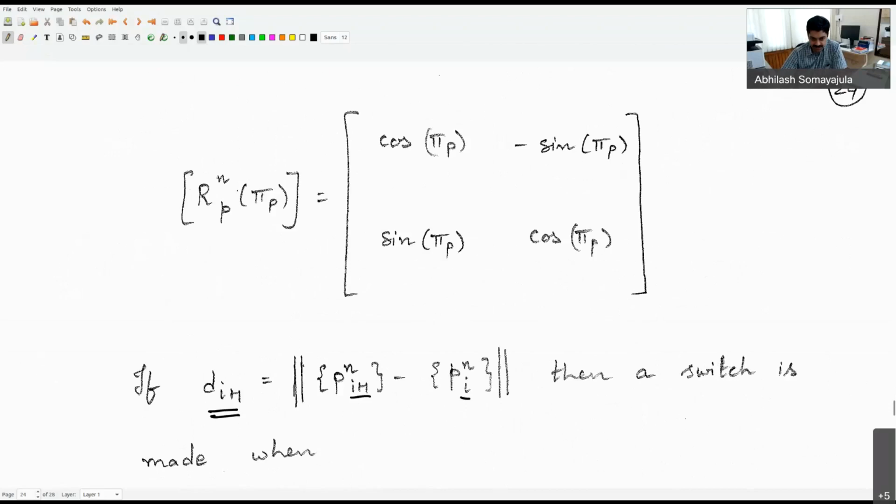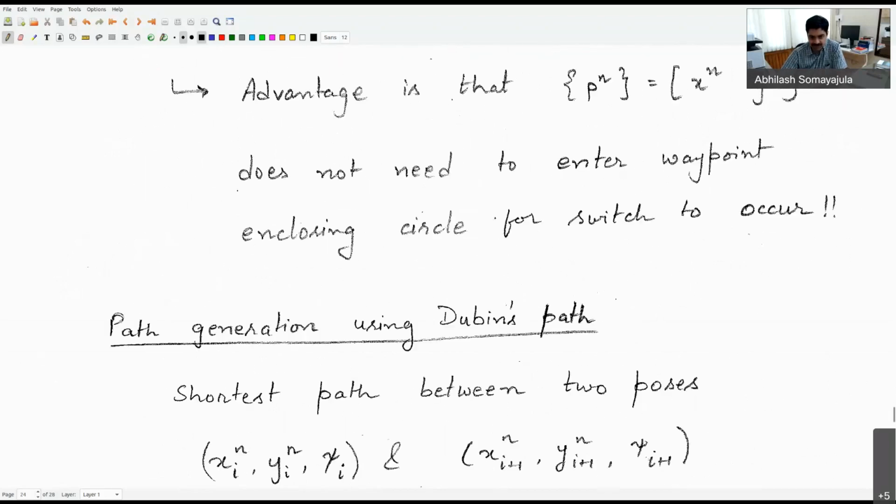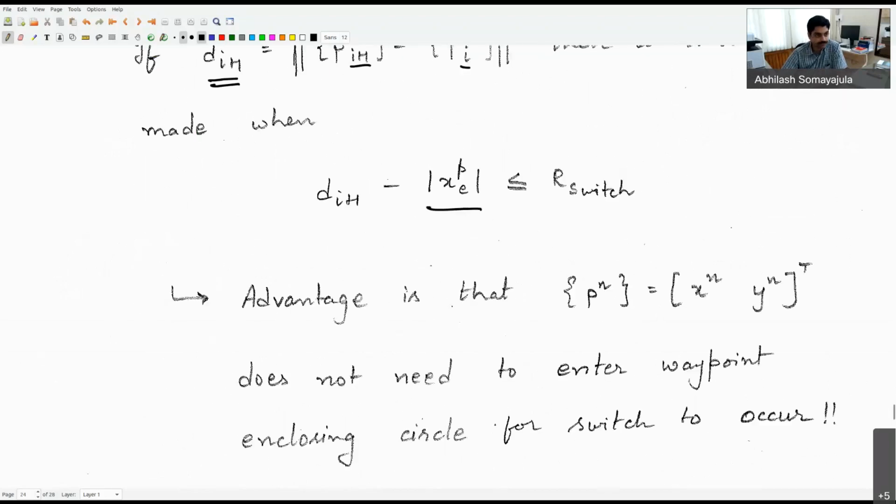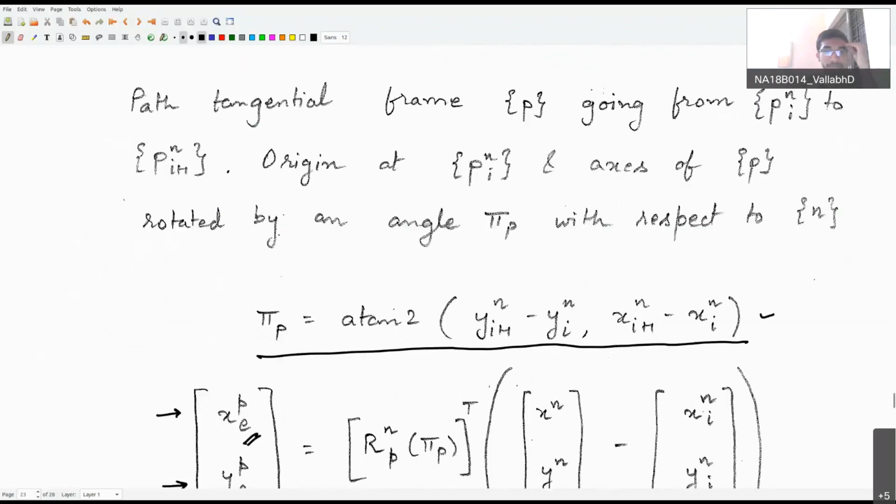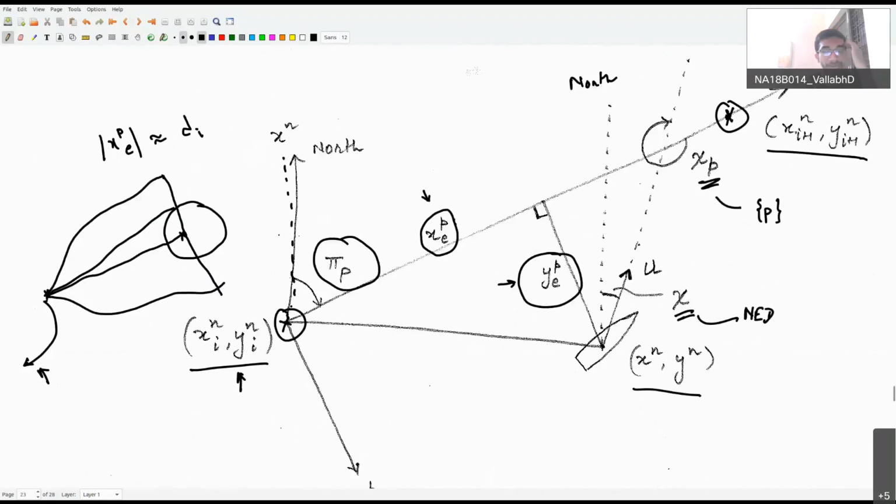Okay, this is where we discuss some of the mathematics of it. Yes. In the above picture, the along track error: if we are calling it an error, when it reaches xi plus 1, yi plus 1, it should be 0, right? No. So it's not technically called an error. Since we call the cross-track error an error, the name has stuck around with it, but it's not really an error. It's how much distance you have proceeded in the along track direction.